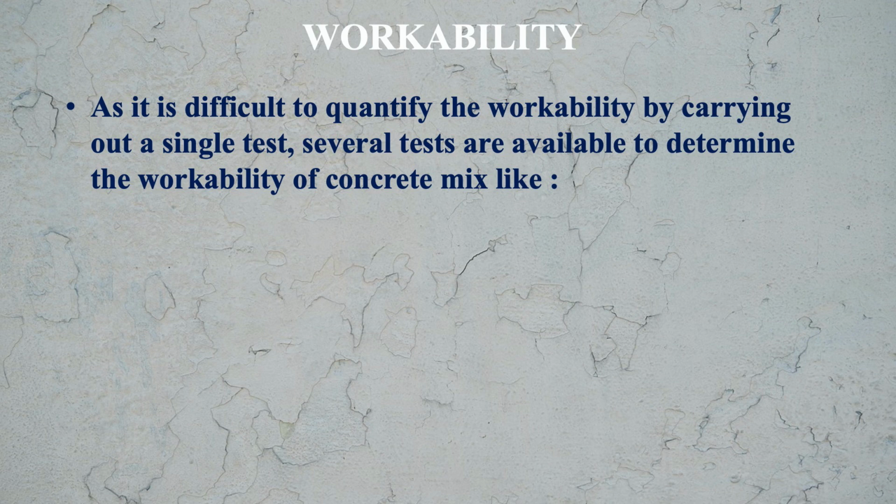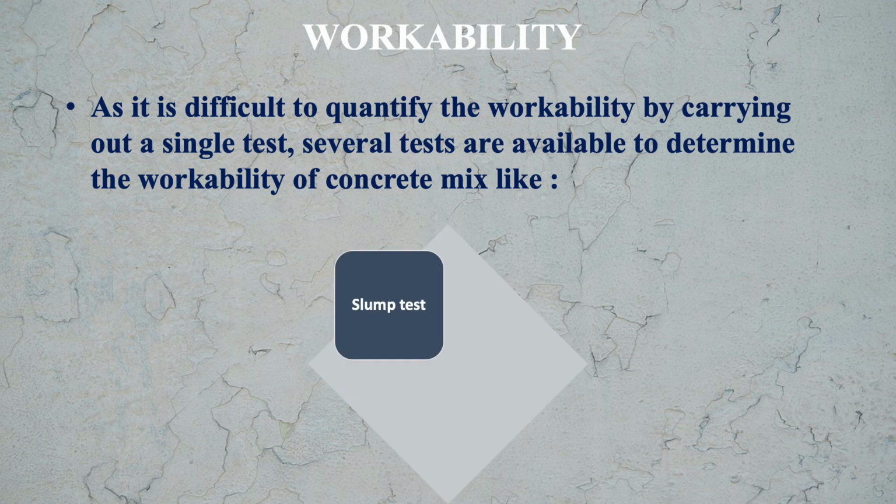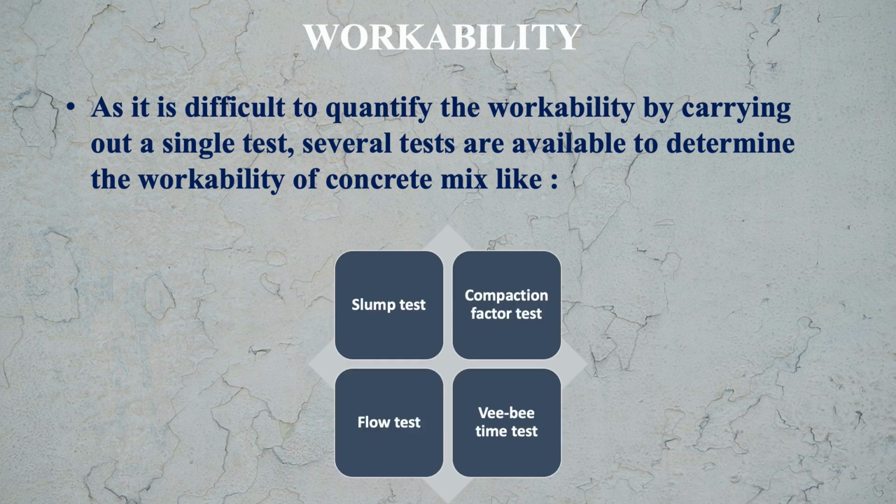As it is difficult to quantify the workability by carrying out a single test, several tests are available to determine the workability of concrete mix, like slump test, compaction factor test, flow test, VB consistometer test. So these are the tests which we can use for measuring the workability of the concrete. Let us see what are the factors affecting the workability.